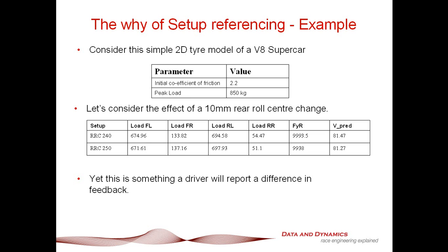So you'd think on paper this shouldn't be much of a change, yet in reality, when we apply a 10 mil rear roll center change to a V8 supercar, the driver can report it back as a discernible difference in feel. Now, what the driver reports and what actually happens, as any practicing race engineer worth their salt will know, will always have a little bit of a disconnect.